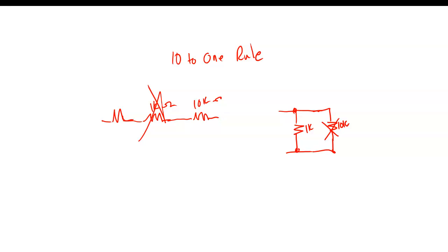But we have to be real careful when we try to put these 2-wire solid state sensors. Now, when we get into 3-wire solid state sensors, the voltage across is going to be a lot less. And why is that? Because it's 3 wires. They're not powered through the load. They're powered individually, right? So they don't have to develop power. So we're going to measure that.